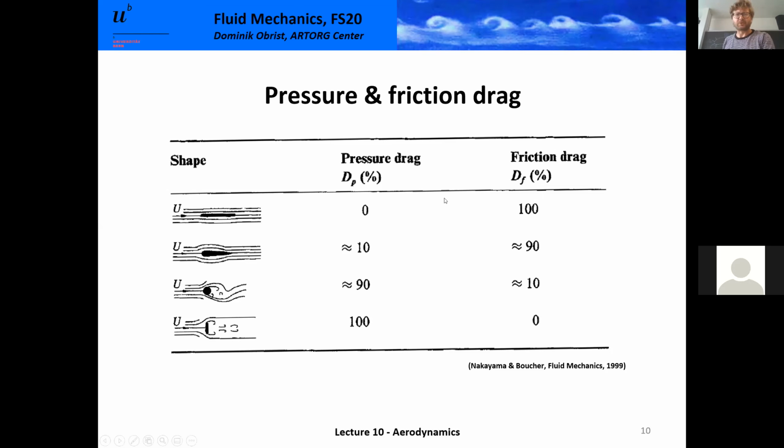Yes, there is, but because the plate is perfectly perpendicular, the shear stresses will be perpendicular to the oncoming flow. So if they can create anything, they would certainly not contribute to the drag because drag is only parallel to the main flow direction.